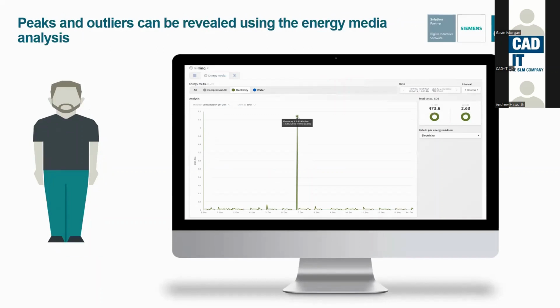The energy media analysis tool shows the electricity consumption and CO2 equivalent and cost for a specific process within the brewery over a period of time. After finding deviations in the regression analysis earlier, it now checks the electricity consumption for all processes to see which one shows anomalies. So from the Sankey diagram earlier on the factory overview dashboard, he knows that the biggest consumers of electricity are the chiller, mixer, and purifier, but they do not show the anomalies, simply that they are the biggest consumers.